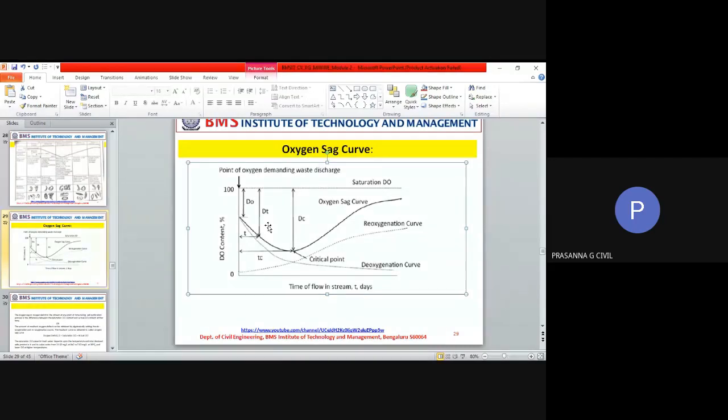This one small thing you can keep in mind will give you a very big reference. Whatever temperature people talk about in between, you may not be able to guess the exact value. It's not needed also because there are calibrated graphs. But when you know that at 0 degrees you have 14.6, and at 30 degrees Celsius your DO concentration comes to 7.63, then you know, at least by interpolating, what value your DO will be for a particular temperature.